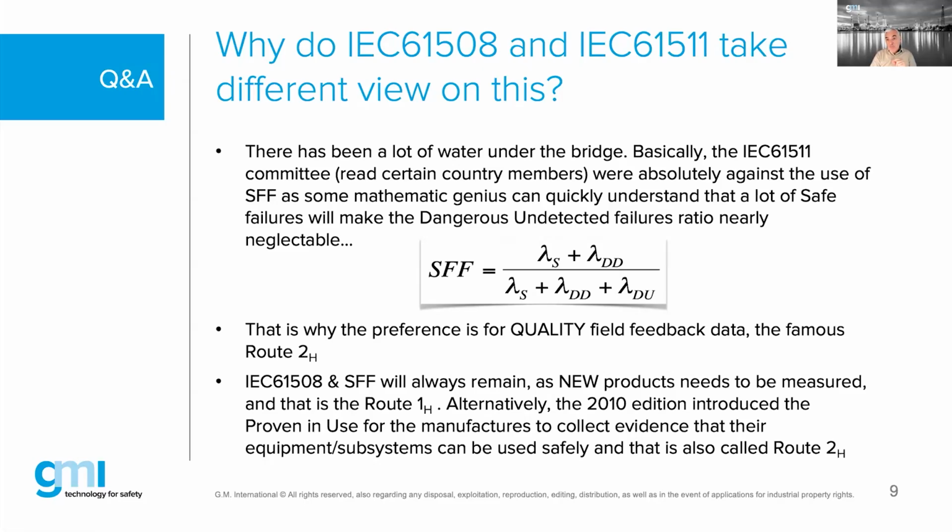However, those mathematics specialists knew that when they put in here 1 million FITs, and FIT stands for failure in time, which is 10 to the minus 9, and you put only 5 dangerous FITs in here, I bet you money that your safe failure fraction is 99.999999 something. That means, since safe failure fraction was by some, let's say, geniuses misleading or manipulated in their favor to go to a higher safe failure fraction, the committee said, we don't trust that.